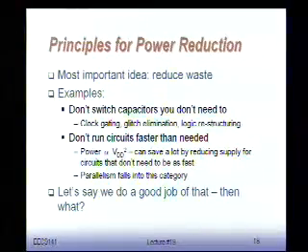So, good. That's kind of the basic analysis. Remember, the basic message is: look first of all at the conditionals, try to compute switching activities, and then add some temporal effects, which is basically glitching. Glitching is purely the result of temporal effects, of timing effects.